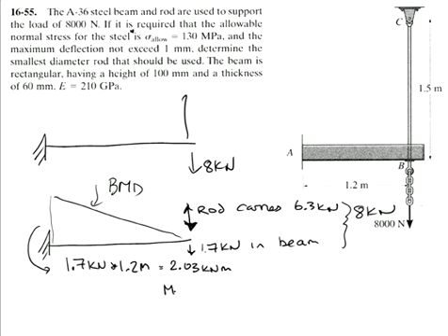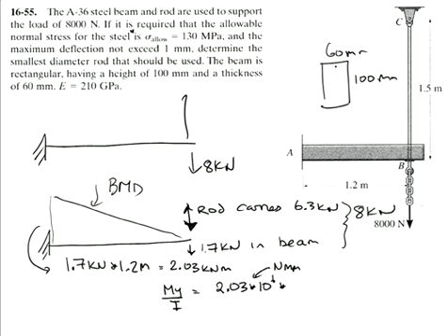So now, when I work out my on I, that's my moment, and I'm going to convert to Newton millimetres times y. And what is y? Remember our beam is 100 mil deep. So y is equal to 50 mil, half the section depth, and I is equal to BD cubed on 12, which if I convert back to millimetres to the fourth is equal to that.